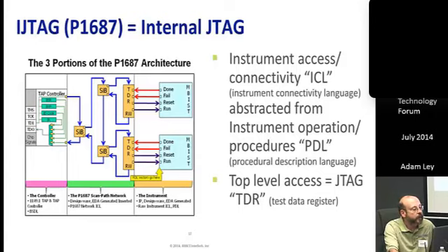So in combination, those bring data onto the chip to access various instruction and data registers to implement the test or other functionality. And of course then there's a TDO to bring data off the chip. One of the things that's illustrated here as a predominant feature of 1149.1 is the boundary scan register. The boundary scan register is simply a shift register that intervenes at the boundary between the non-test pins, the system pins as they're called, and the internal logic that they feed or are fed from.